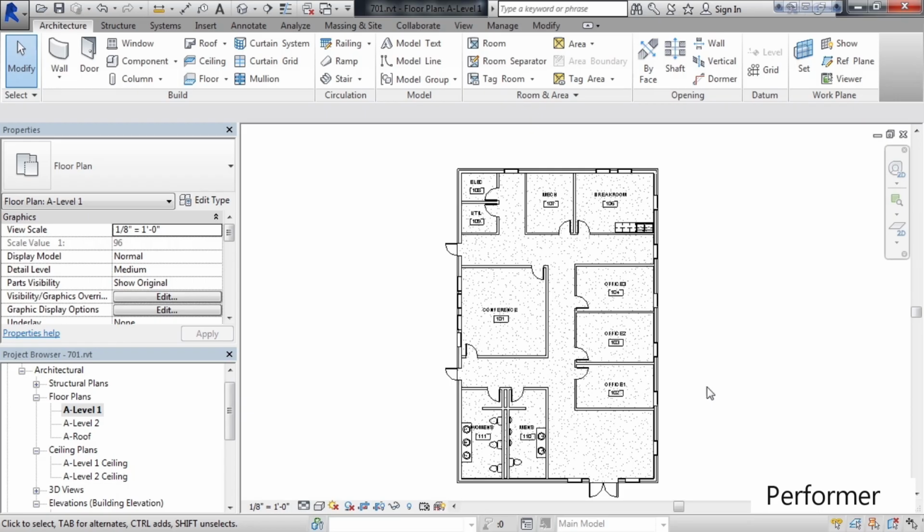Another option we looked at was going to a room schedule table that's already been defined and adding our rooms there before they're actually placed. Once we added our rooms to the schedule table, we then went back to our model and placed our rooms, but made sure we selected the room from the room dropdown which we wanted to place in that actual space.